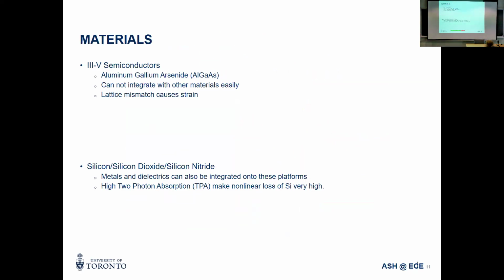So there's a couple of different material platforms I'm going to talk about with doing this. The first is for entanglement, where we're focused on Chi2 materials, where we have aluminum gallium arsenide, which is highly tunable with the doping concentrations of your aluminum compared to your arsenic. You can vary that highly using MOCVD, and you can make quantum wells by growing these things and get all sorts of cool structures and actually get on-chip lasing with these as well, which I'm going to talk about in the next couple of slides.